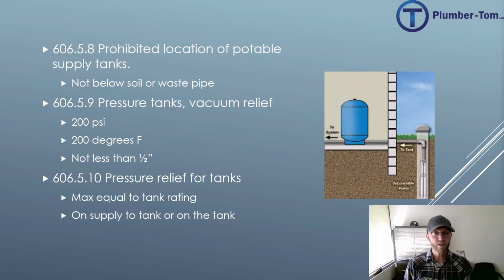606.5.9, pressure tanks do have certain ratings. They have to be able to handle 200 psi at 200 degrees Fahrenheit. And the size of the vacuum relief valve would have to be not less than ½ of an inch.